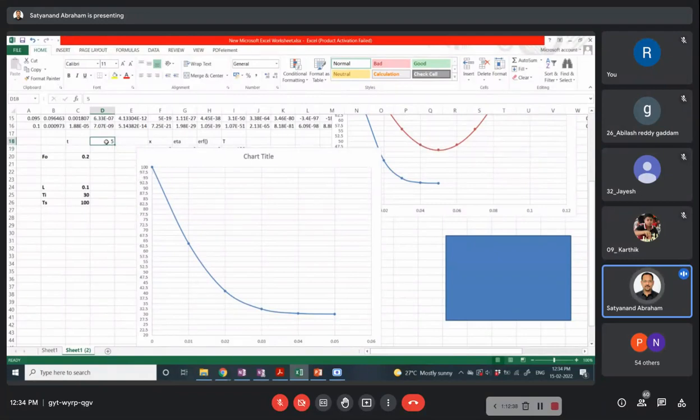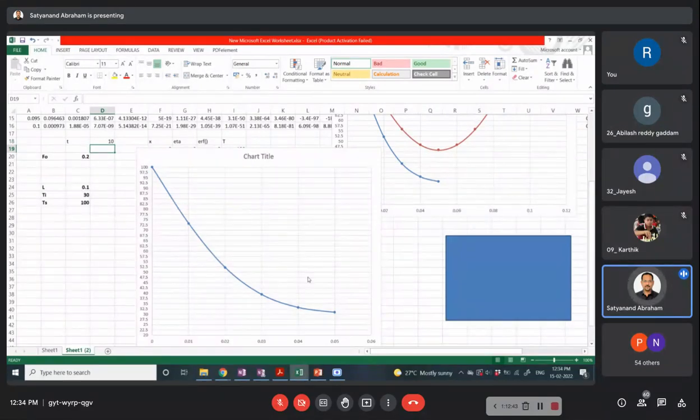Now, if I increase to say 10 seconds, you can see that the temperature even at x equal to infinity... So in this case, we are saying the maximum it can go up to is 5 centimeter only, right? So here you can see that now the maximum possible x starts to feel the boundary conditions. So for any condition more than say 7 seconds or something, the full body is now feeling the change in the boundary condition.